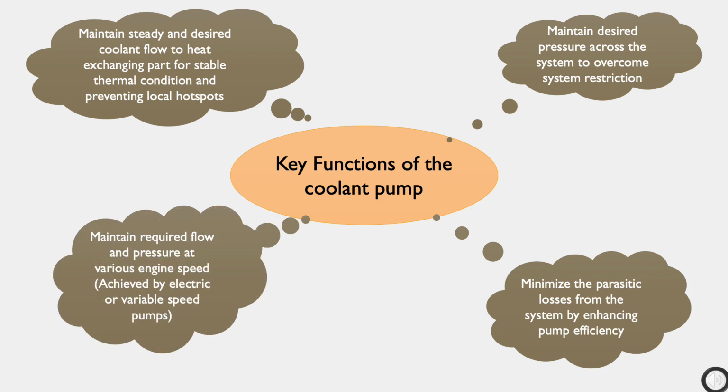And lastly, the coolant pump needs to work across all operating conditions. Common coolant pump performance depends on engine speed. The higher the engine speed, the faster the pump spins, and the higher the flow it generates. However, in some applications, the pump needs to perform independently of engine speed. This is normally achieved by an electric or variable speed pump.